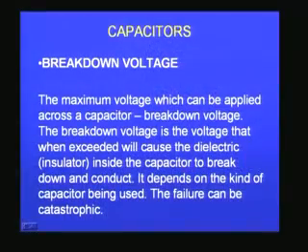So breakdown voltage is one other important characteristic of capacitors, and therefore when I buy a capacitor, I should specify the operating voltage. If I am going to operate the capacitors at 6 volts, 12 volts, etc., then I can go for 25 volt capacitors or 50 volt capacitors, as the case may be. But if I am going to operate the capacitors in regions where the voltages could be as high as 1000 volts or 2000 volts, then I should buy capacitors with very large breakdown voltages of the order of 5 kV or 10 kV and things like that.